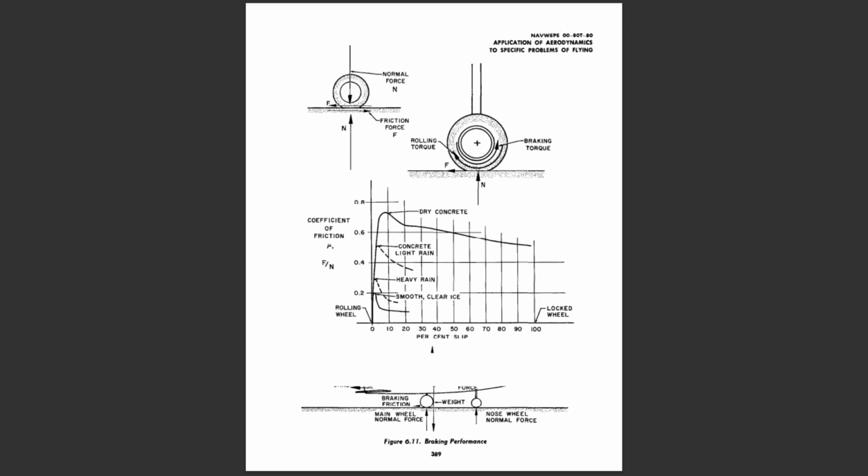The combined effect of flap retraction and aft stick is a significant increase in braking friction force. Of course, the flaps should not be retracted while still airborne, and aft stick should be used just enough without lifting the nose wheel off the runway. These techniques are to no avail if proper use of the brakes does not produce the maximum coefficient of friction.